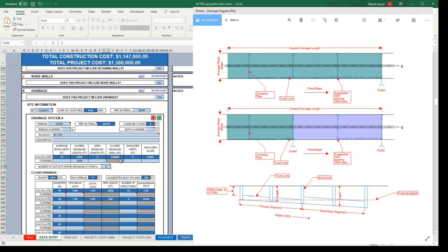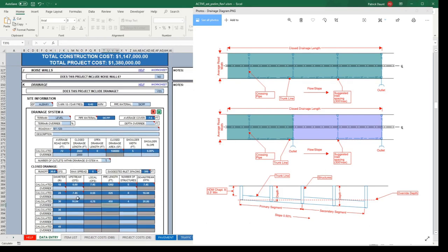So you'll see here, if I go back to 1, we go all the way up to a 30-inch pipe, whereas if I put in an intermediate outlet, we no longer need a 30-inch pipe. Furthermore, you'll see the pipe lengths will double essentially. So we had 1,300 feet of 18-inch pipe here. If we put in an intermediate outlet, we now have 2,000 feet of 18-inch pipe.